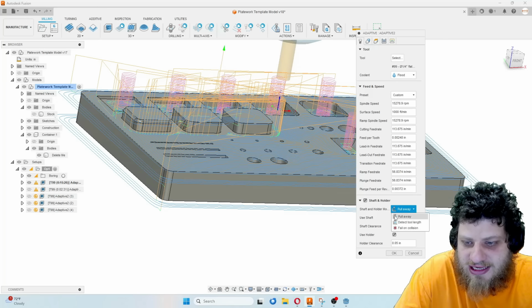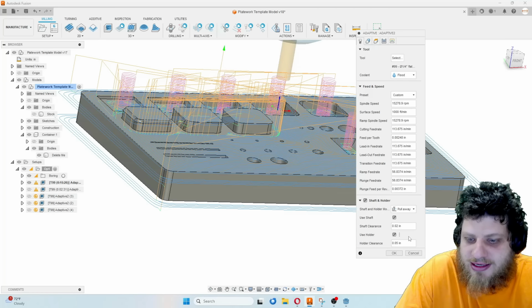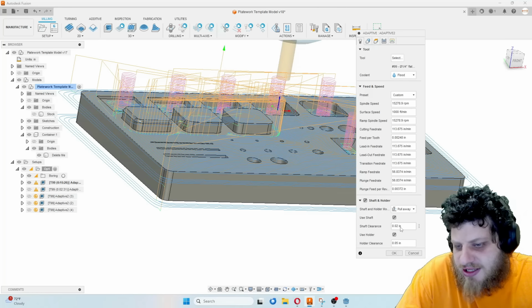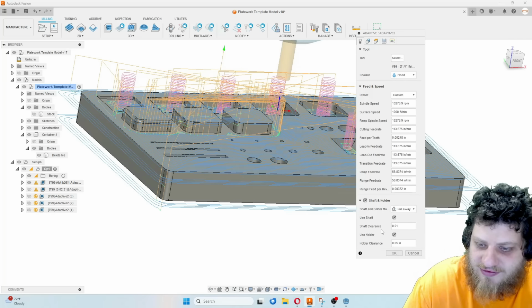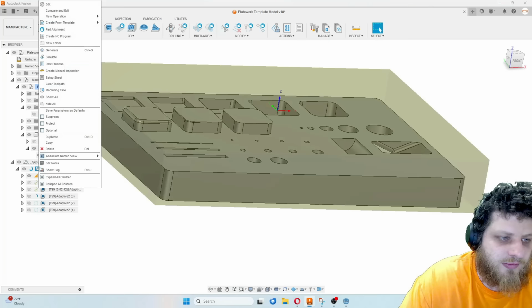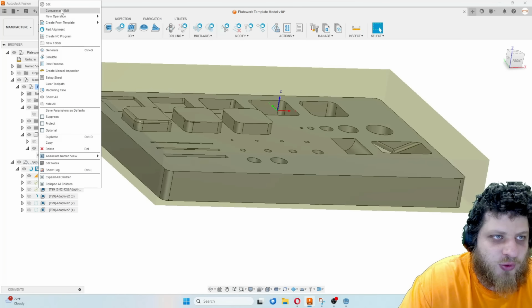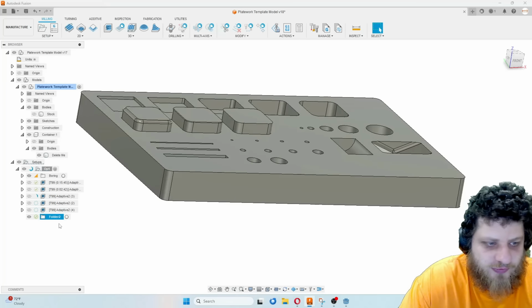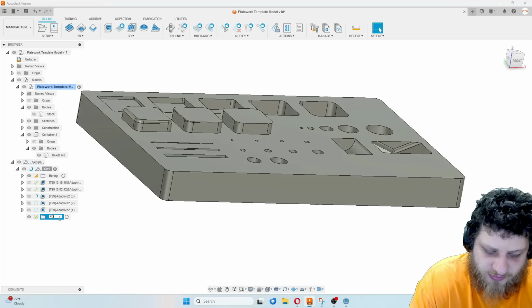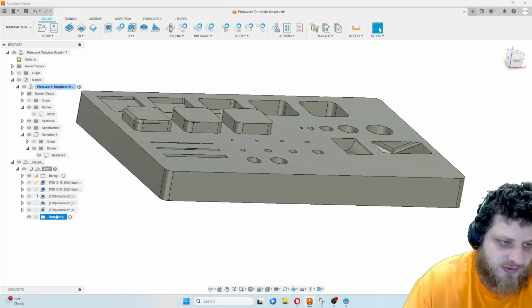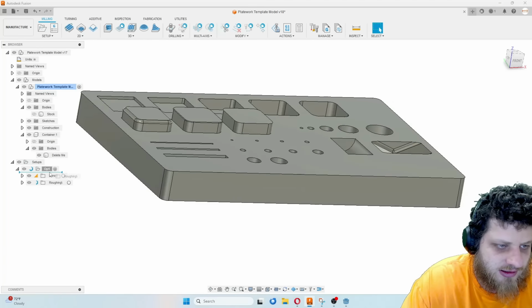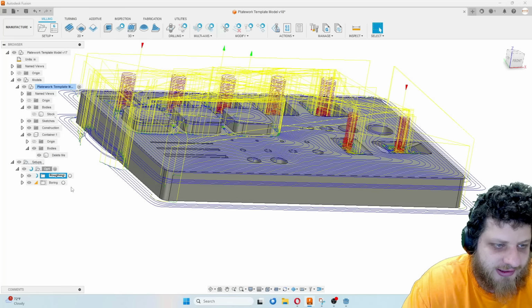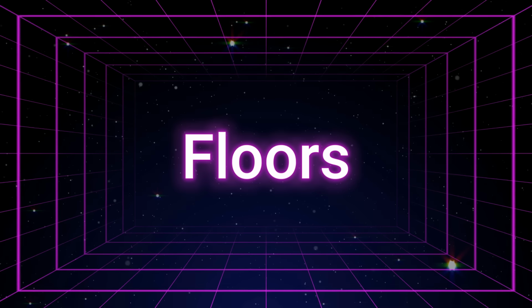So I like to use it in this pull away mode, and the clearances are about as shown here. 0.02 may be a little bit high on the shaft. We can go down to 0.01. And just like before, we will add those to a new folder called roughing. We'll put our toolpaths in it, put it above our boring, and get rid of our typo again.